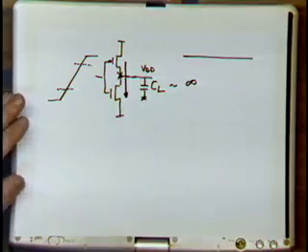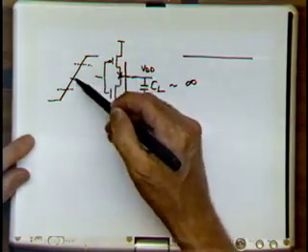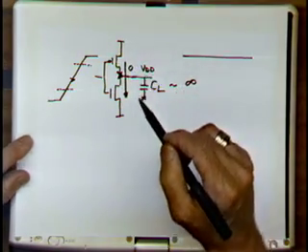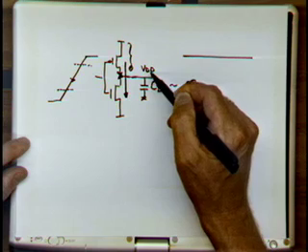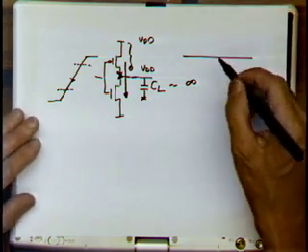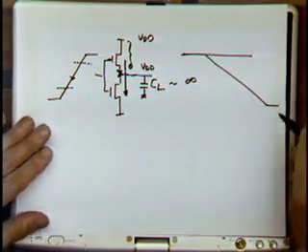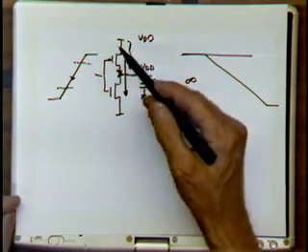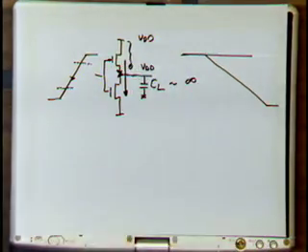So what short circuit, basically, I turn this on. I'm basically going to this period here. I turn on the NMOS. But the VDS of the PMOS stays at VDD, so you have 0 voltage over the PMOS device. If you have 0 voltage, no current will flow through it. So actually your short circuit current is going to be 0. This is typically the case when I make the output slope very slow compared to the input slope, because before we really get through it, this thing will never really have a lot of current flowing through it.